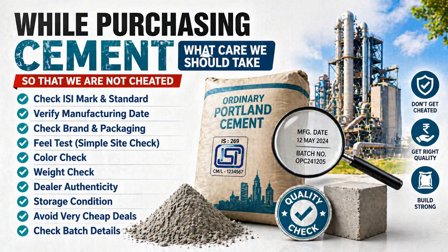Perform a simple field test by rubbing cement between your fingers. It should feel smooth and free from lumps, as lumps indicate moisture damage. The color should be uniform grey with a slight greenish shade, and the standard bag weight should be 50 kg. Random weighing can help us verify the weight of the bag. Purchase only from authorized dealers and always take a proper bill or invoice for authenticity.